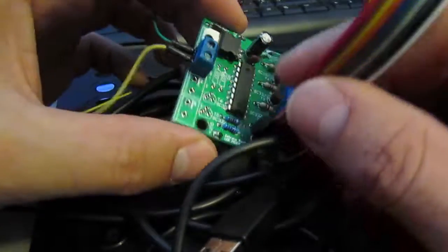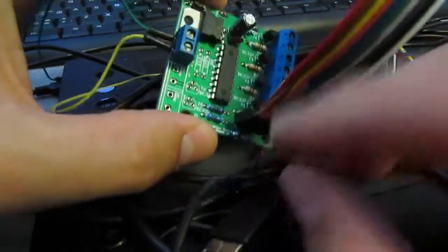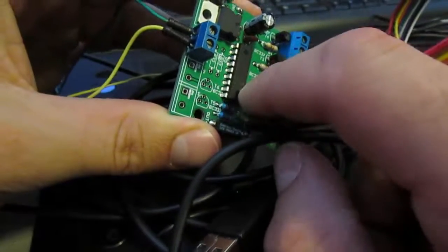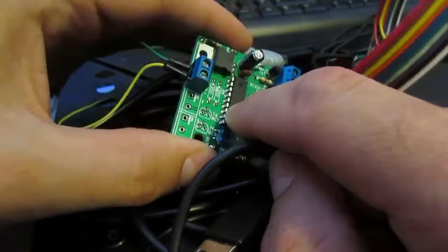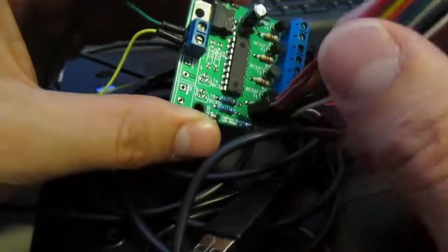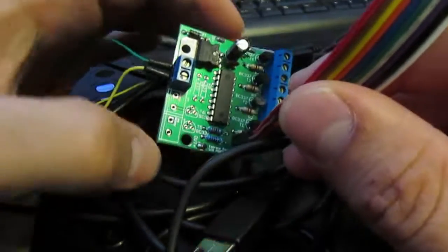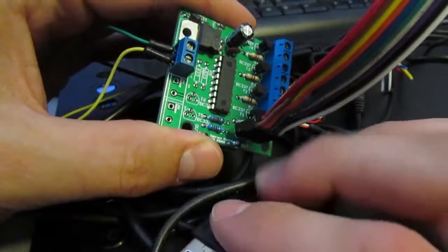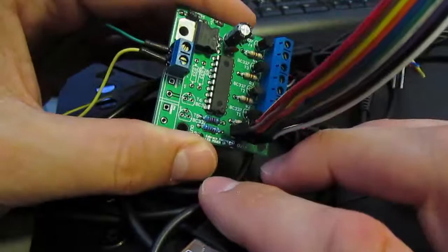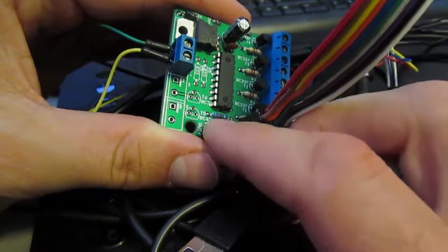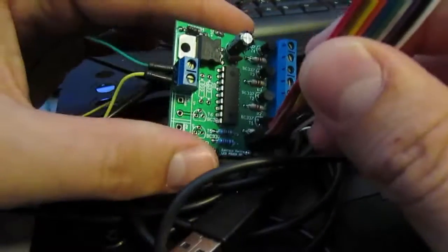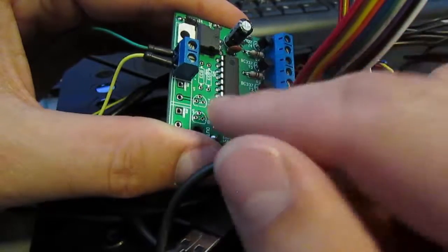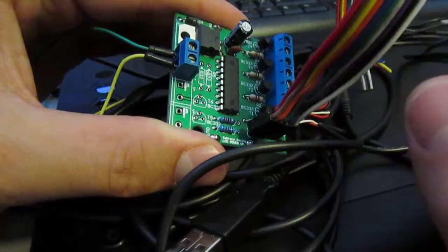microcontroller. And like I mentioned in the first video, in the schematic, there's a few resistors that are responsible for handling the logic to program this controller, and it's all built into the board, so you don't even have to buy that other board. It's so easy to do. And even in the PICAXE documentation, which I showed you again in the first video, it shows you the circuit, and like I said, we've built it into this board, so you can program this as many times as you'd like, and you never have to remove your PICAXE.